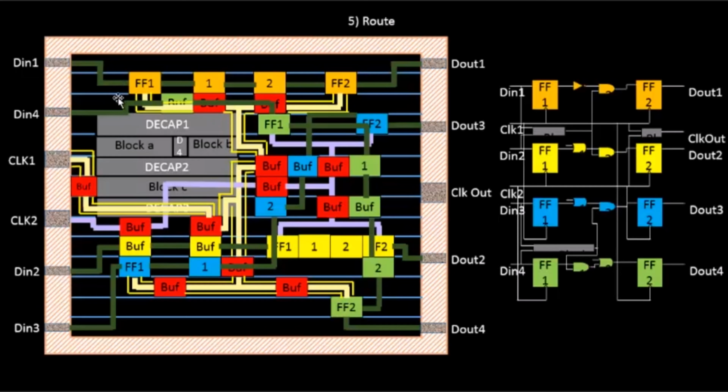That's the function of the timing-driven routing engine. For example, there was a timing scenario from flip-flop 1 to flip-flop 2 with the help of this clock tree. The route engine will make sure that the timing scenario from the CTS stage is not deteriorated. That's how the route has to be.